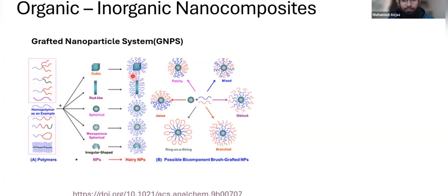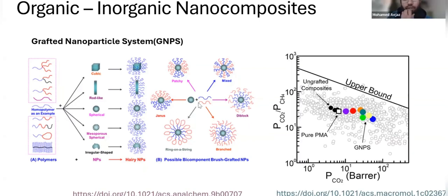You end up creating a polymer nanocomposite that people usually refer to as hairy nanoparticles, because once you add these nanofillers to your polymer, you end up creating a structure that looks more like a core-shell structure. You have a nanofiller in the center, and then the chains are grafted onto the surface of these nanofillers, and then they extend out from the surface. If you have a polymer that is bicomponent in nature, the best examples being polymer blends or copolymers, where you have two different kinds of polymer chains, and then you also add a nanofiller, then you create structures that are really, really diverse microscopically.